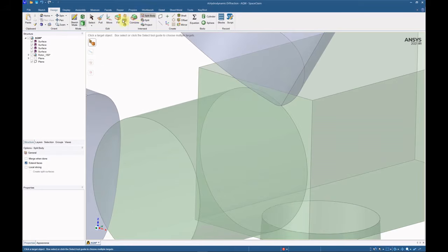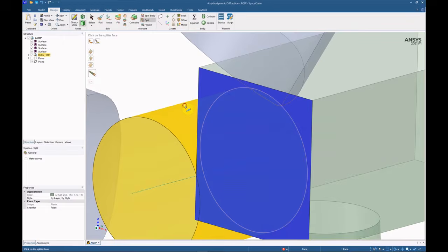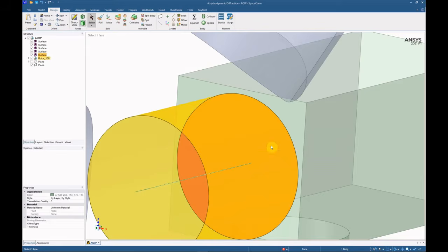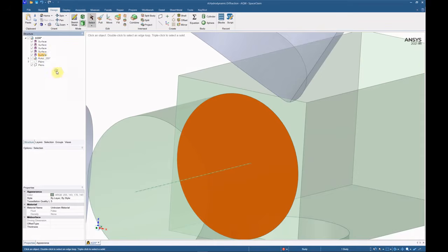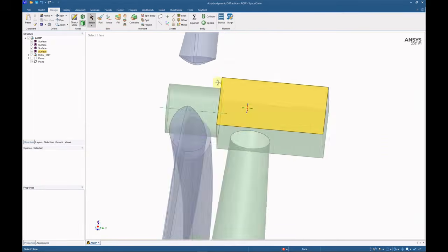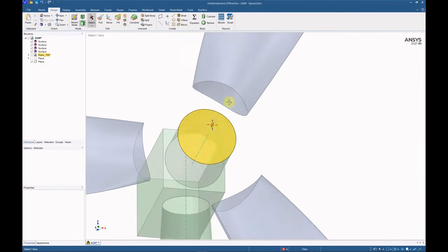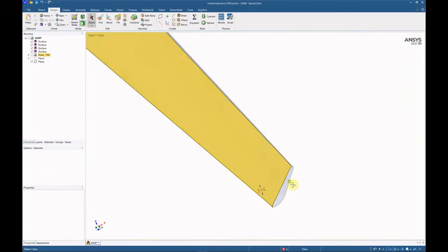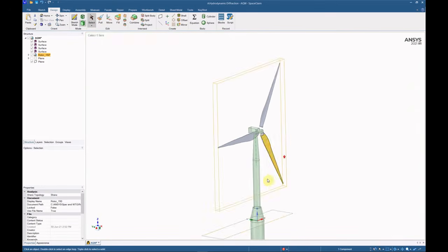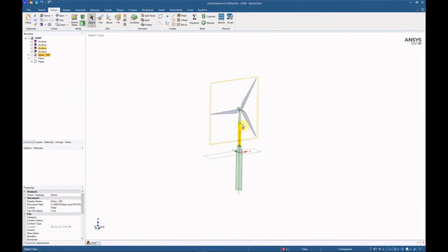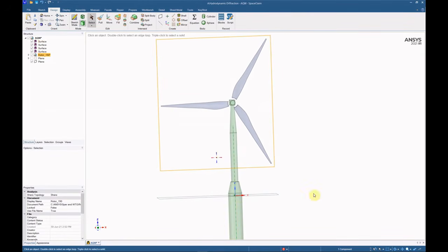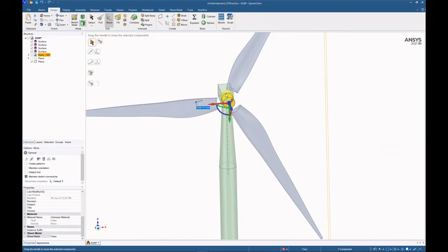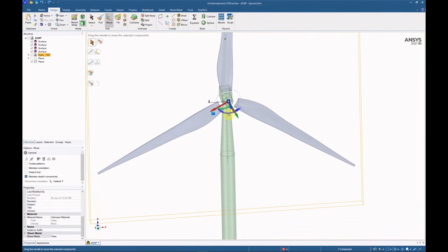Use the split tool on the nacelle front face to make sure the hub and the nacelle share nodes on the edges. Blade tips were cut out to improve mesh operation. With the move tool centered on the hub, we can rotate the rotor to a new position.